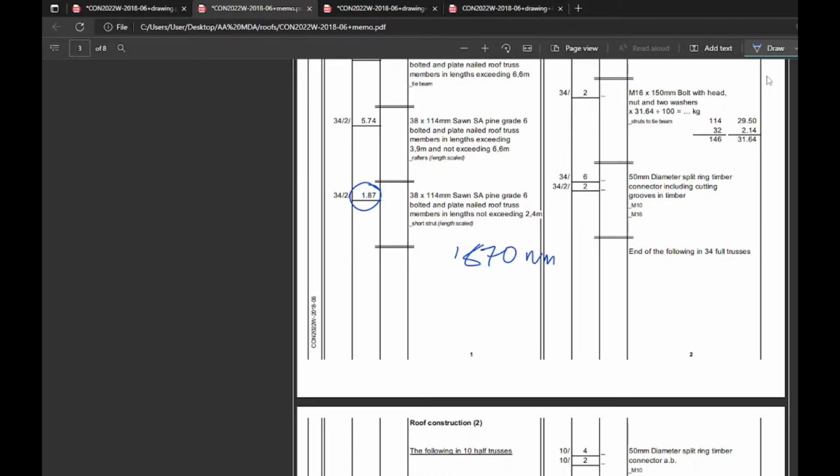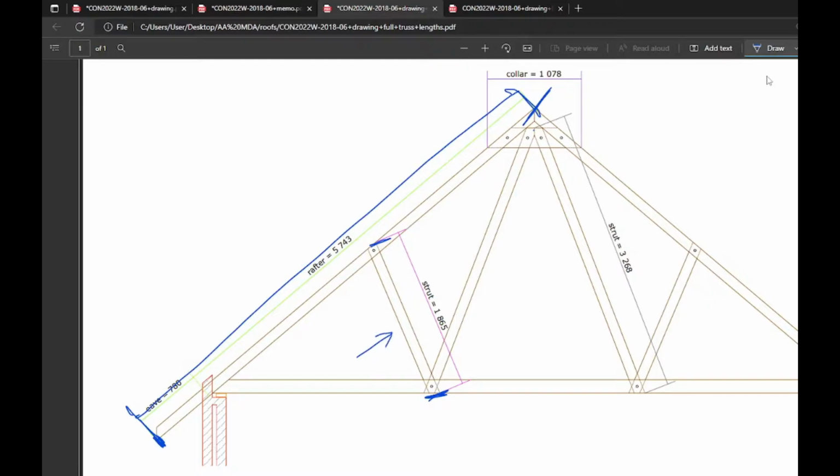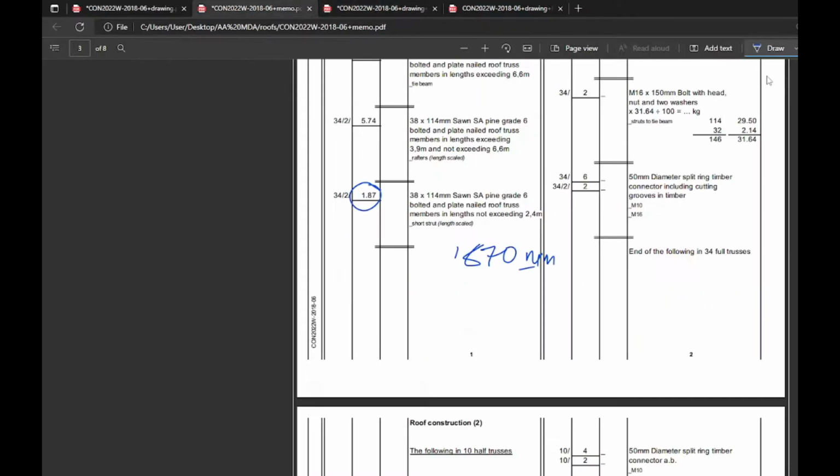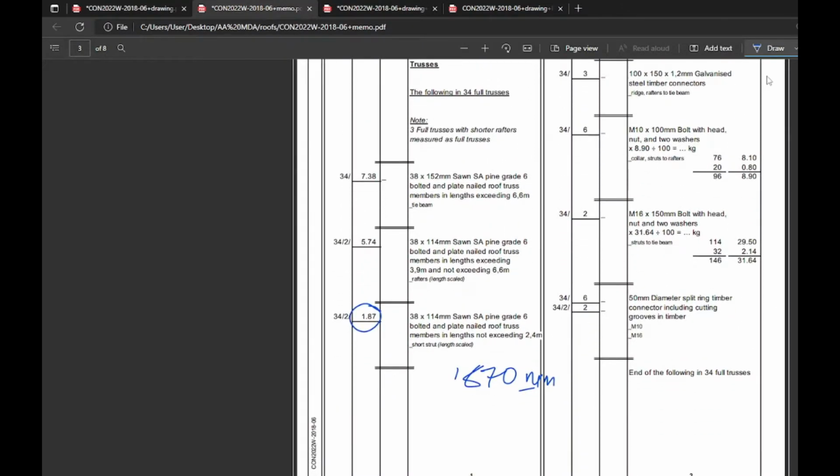Okay, so let's just reverse engineer this. If this is 1,870 on a 1 to 25 scale, that means this real measurement on paper is 1865 divided by 24, right? And you'll get what she measured with the ruler. Same theory, just working backwards. There we go. Clean up a bit. That's pretty clean.